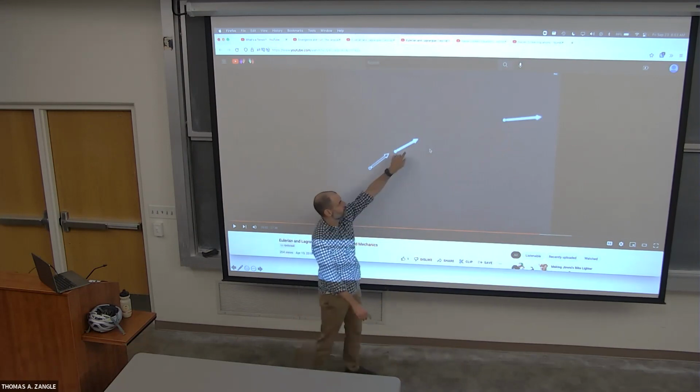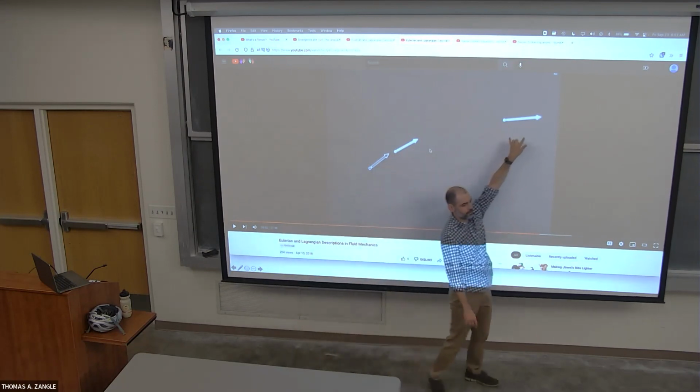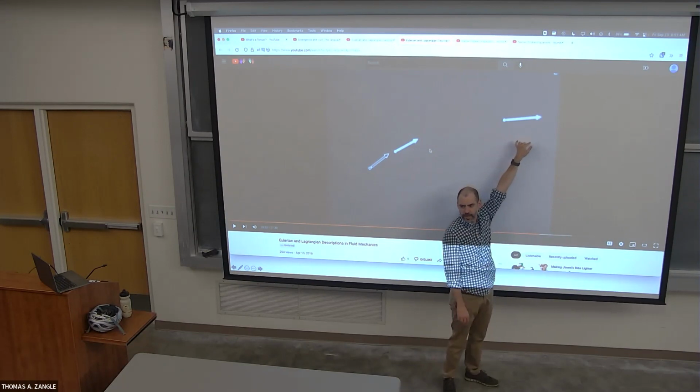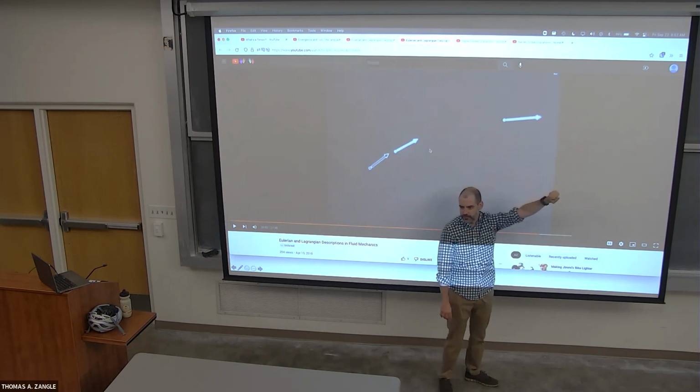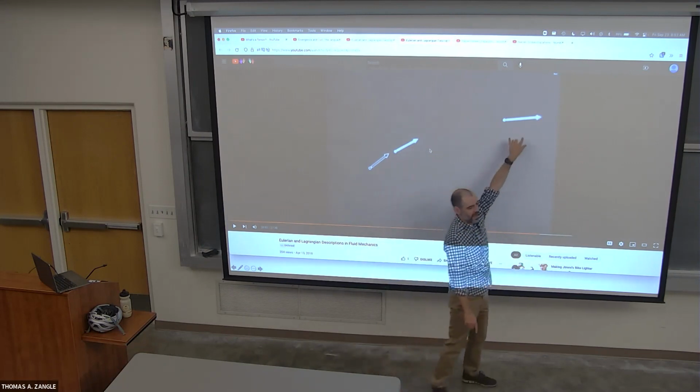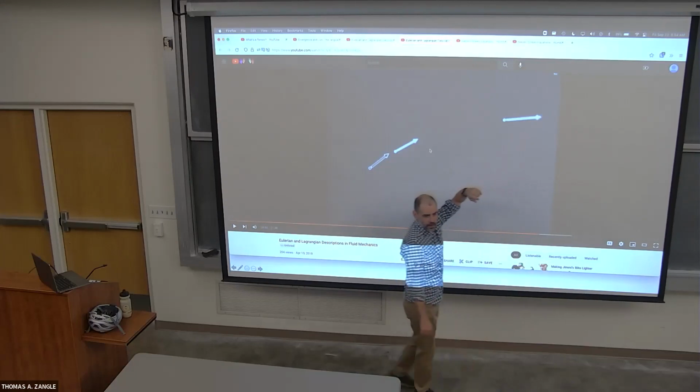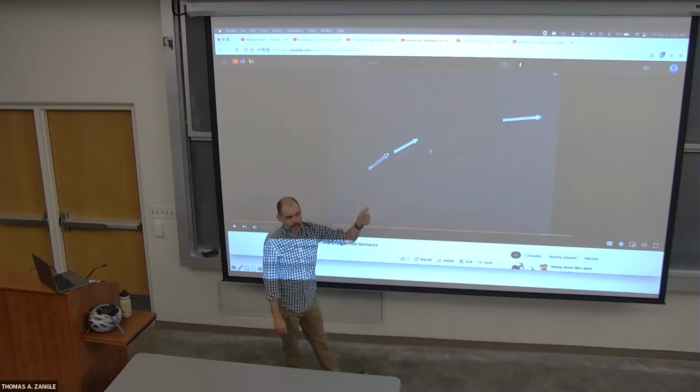So the first is that the length of this vector here is larger. We can think of that as in that converging flow. We got a smaller area, and therefore there is a higher velocity at the exit, and therefore the magnitude of this is larger. But remember, velocity is a vector, so when we say acceleration, a change in the direction is also an acceleration.